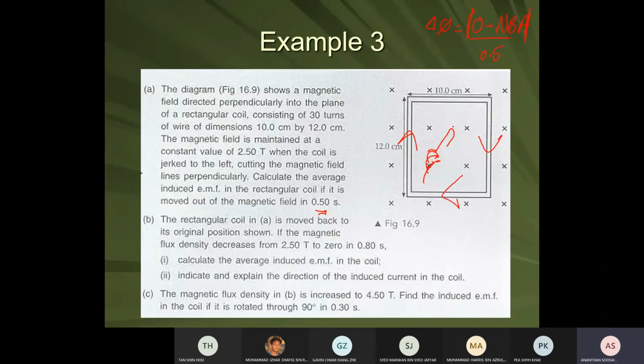So the current should flow this way, as if there is a battery generated at this edge. Then the current will be induced in a clockwise direction when you move this coil away from this magnetic field. Any questions, guys? Those who found the current should be clockwise, good. Understand which direction to show the current? Use Lenz's law.